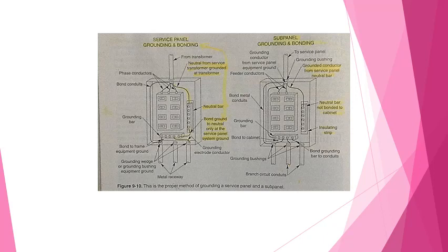Must be in readily accessible locations: receptacles in bathrooms and outdoors where there is direct grade access, including bathrooms in motel guest rooms, unfinished basement receptacles, all kitchen countertop receptacles, crawl spaces if at grade or below grade, wet bar sinks, all receptacles in garages, and receptacles that are not part of permanent wiring, such as those used for temporary power during construction.